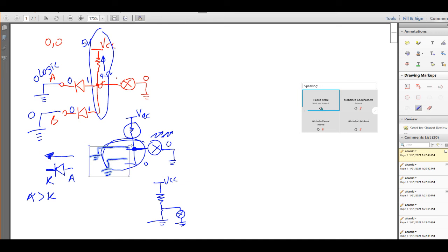All this section here is 1 node, 1 point. The wire here doesn't have any resistor. So this point, this point, and so on, all along this wire, and this wire, and this wire will be the same. That's the node. Clear? Yeah, because they are parallel, they are at the same point. If you take a voltmeter and put your probe here, or here, or anywhere, they will show the same value, meaning the same point. It's just extended by wires, and that's it.